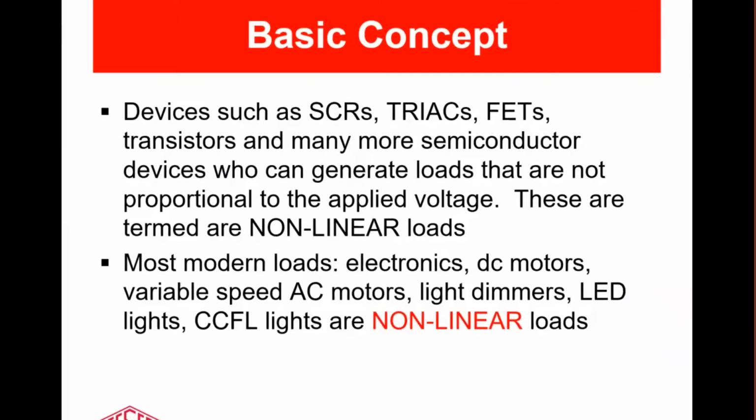The compendium in C12.24 are a lot of waveforms that have been measured in the field. Most of them come from NRC Canada in a study they did about 20 years ago. The waveforms that I'm showing here are the ones that appear in the standard and are used for testing the harmonic performance of meters. And we'll talk about that a little bit more when we get further into the presentation.